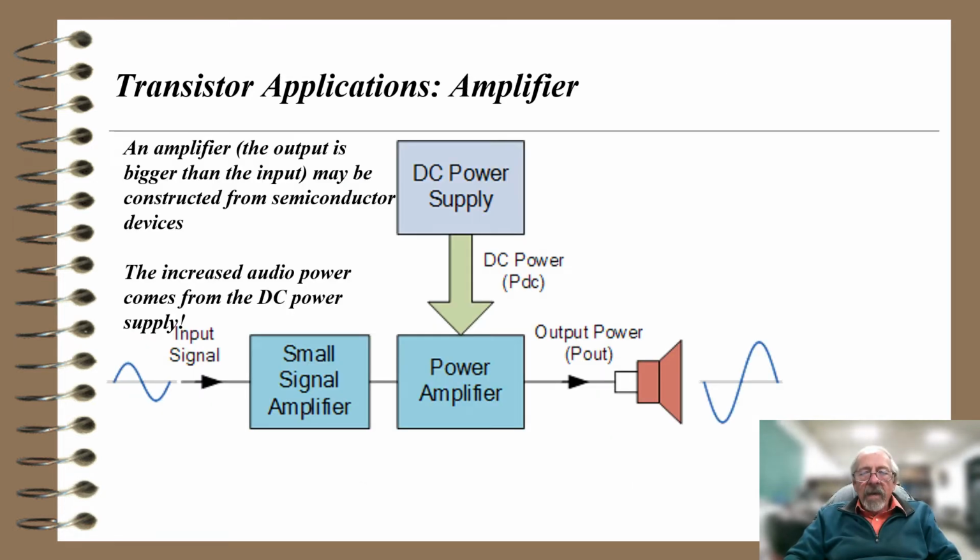So what are some of the applications of transistors? Well, transistors, bipolar junction transistors, and field effect transistors are not easy to set up in circuits. I should point that out first. It turns out you have to bias these things, which means putting different voltages on in the bipolar junction transistor, the base, the collector, and the emitter. And the same thing with a field effect. You have to have various voltages, as we mentioned, to turn things on. So it's not an easy thing. We used to spend semesters learning how to bias transistors to make them into useful things.